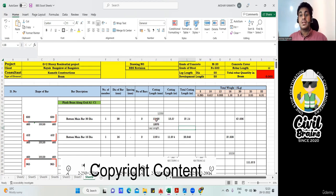It's a total cutting length. Imagine, what is the length of your one rebar? It is 12 meter. But this length has gone beyond 12 meter. So our one straight bar which is available in the market is 12 meter. But here the length we are getting is 12,430, which has gone beyond 12 meter. That means we need to provide lap.